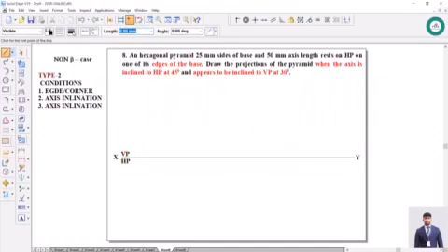To begin with, go to line command, take the suitable type and width, start with a horizontal line. So 25 length, 0 angle, 25, 60, 25, 120, 25, 180, 25, minus 120, 25, and minus 60. After drawing this, identify the center by joining the diagonals.